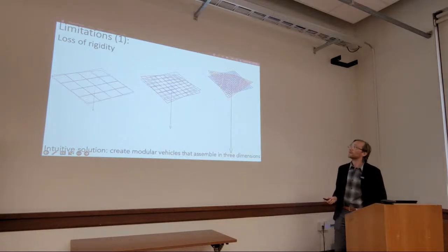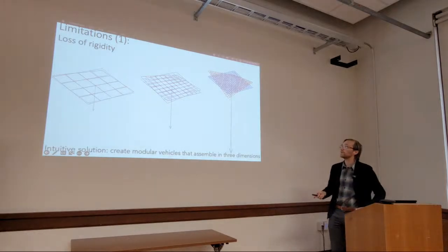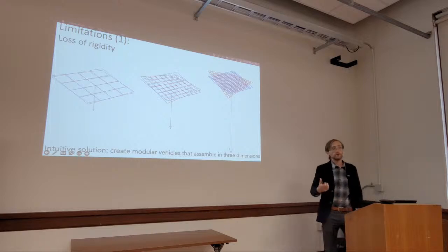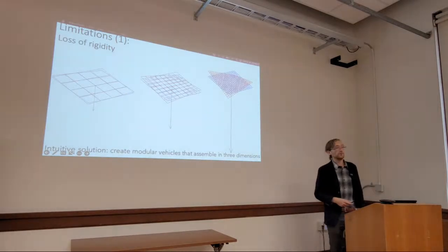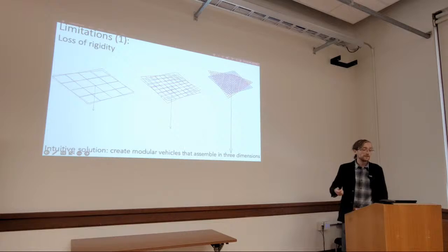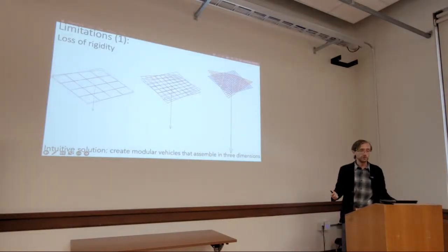If we imagine that we scale up the number of modules and we scale up proportionally a force that is applied to them, where we imagine that we have some payload that is lifted by some flight array, then the amount of bending will increase with the number of modules, and that bending can lead to several issues. A loss of efficiency, because now the rotors are not all parallel, increased stresses that can lead to structural failure, and overall, even just the fact that the structure is less stiff can make it harder to control.